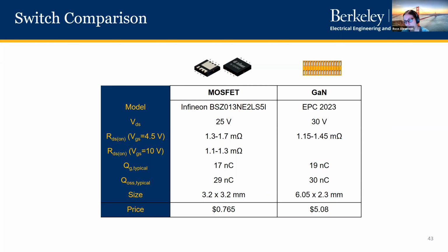So one interesting question is, people often ask what equipment you use to measure it, because if you're just using the power supply readouts or a multimeter, it's very hard to accurately measure 99% efficiency. So we do use a Yokogawa power analyzer to get good accuracy on those numbers. So that's one area people often ask.